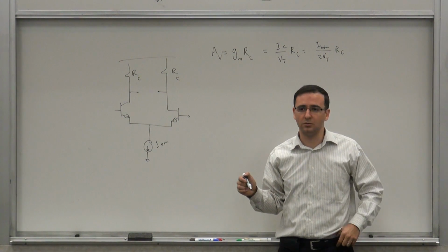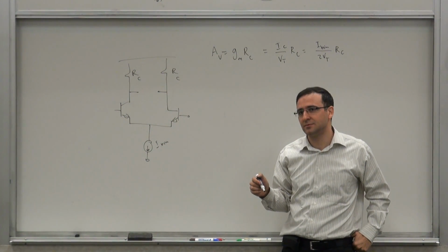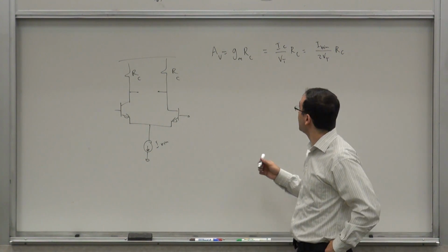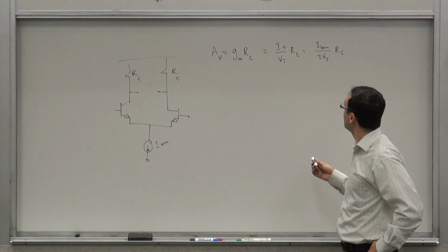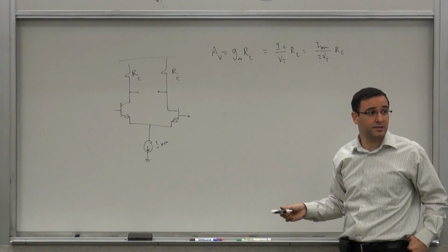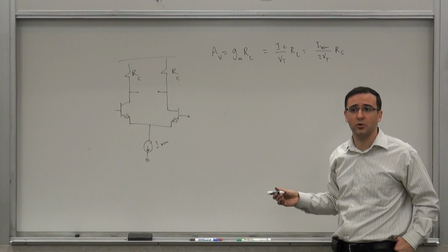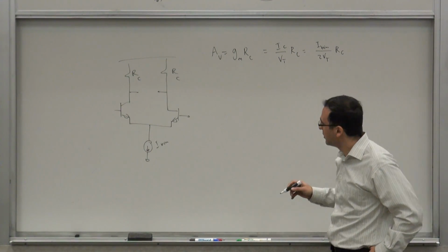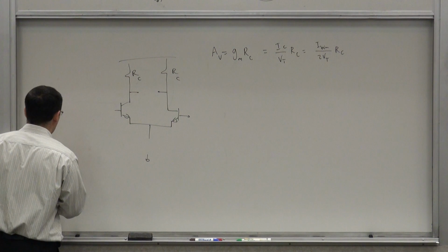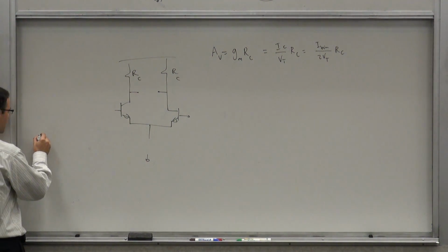Right? So, how would you bias it? You have to use PTAT current for the bias. So first of all, you want something that increases with temperature or decreases with temperature? Increases, because VT is in the denominator, right? So you want I bias to be proportional to VT. So, how do we do that? Help me out. I need to make a VT reference, a PTAT.